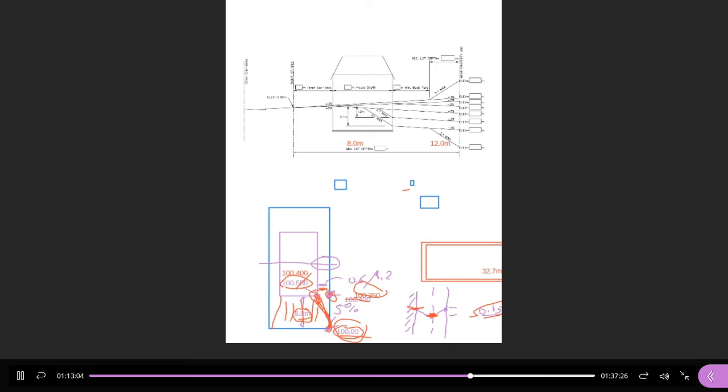So what does that represent? That represents a full walkout house with a full usable backyard. Everybody agree? So if you were going to walk from the front of the lot to the back of the lot through the house, you would walk up the front lawn, take a couple of steps into the first floor, go down the staircase to the basement, walk to the back of the house, step down onto the ground, maybe 1, maximum 2 steps, and then you could walk all the way to the back of the property. Nice slope of 3%.